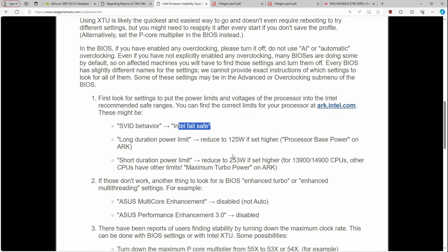And then the other one is electromigration, right? That's the degradation that sort of everybody knows about. That's caused by very high current draw. Electromigration is worse at high operating temperatures. And so if you just set a lower temperature limit, you get lower electromigration. Also, at lower temperatures, if the CPU thermal throttles earlier, it's not going to be able to pull as much power, right? So you're going to have less current. So that's going to reduce the electromigration as well.